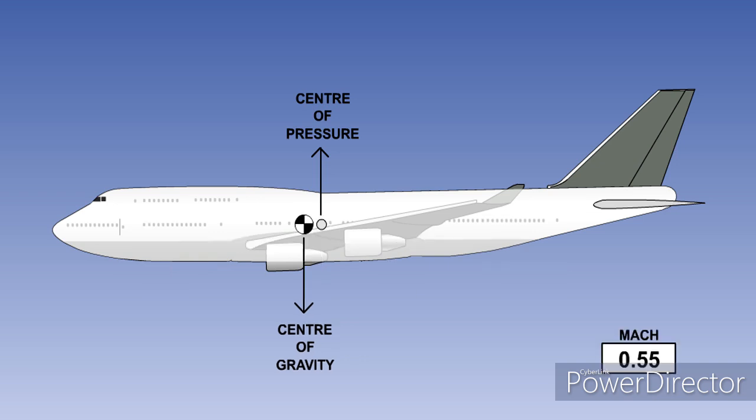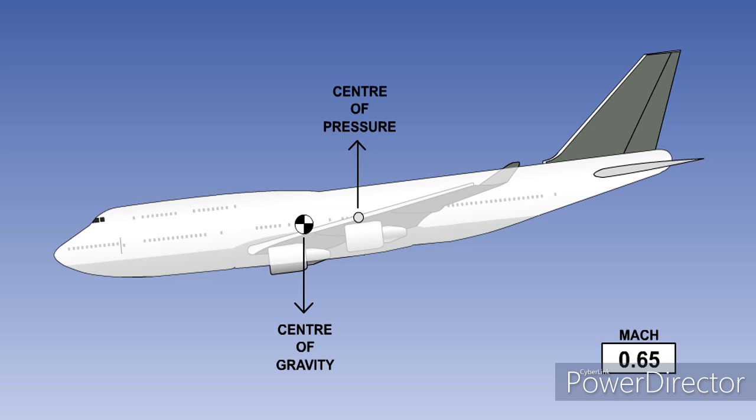On most large turbojet aircraft, the wing centre of pressure moves rearward as the aircraft approaches high subsonic speed, and this produces large nose-down pitching moments, known as tuck-under or Mach tuck. It is essential that the aircraft is fitted with an automatic system to correct this change in pitch attitude.